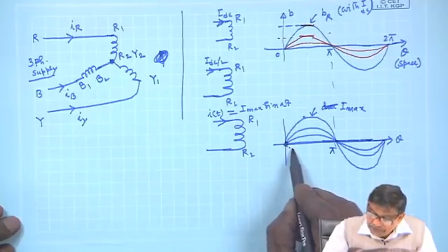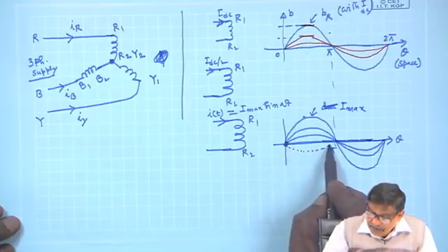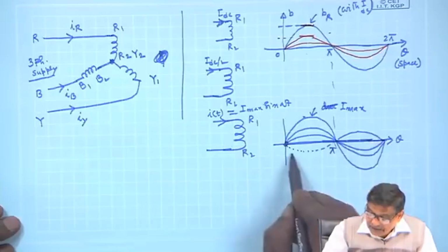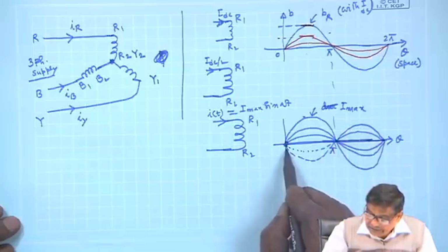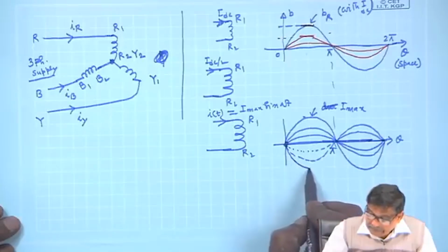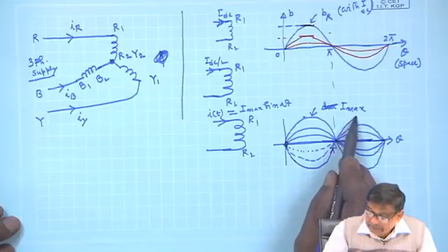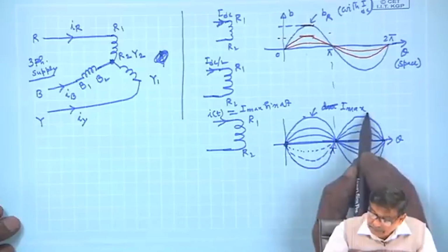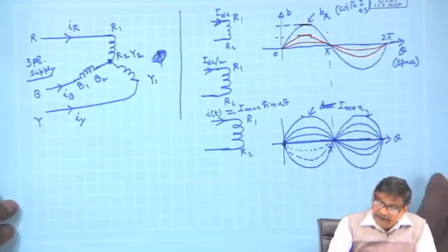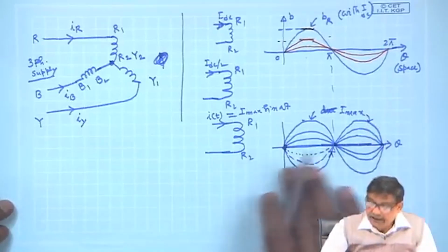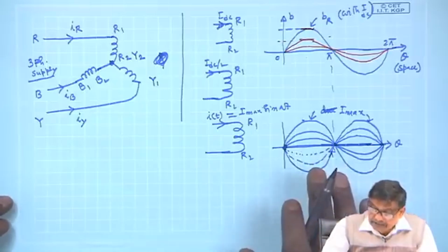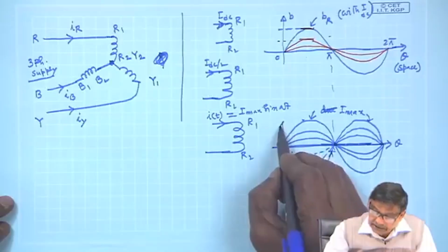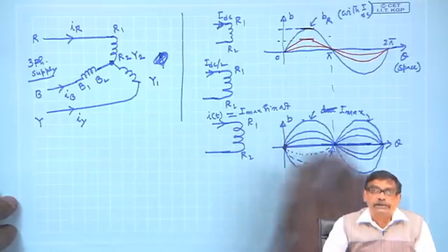Then the polarity of the B will also be negative, depending upon the magnitude of the current. Getting it? So, this will be the kind of wave, MMF distribution or flux density distribution, along the air gap of the machine. We will continue with this. Thank you.